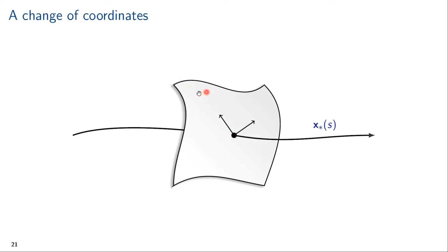Now this lets us introduce what's called a set of transverse coordinates, whose origin corresponds to the nominal solution. If we can stabilize the origin of these so-called transverse coordinates at all points along this hybrid periodic orbit, then we simultaneously stabilize this orbit as well.